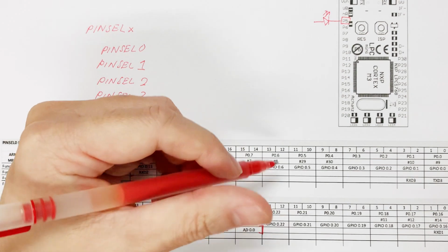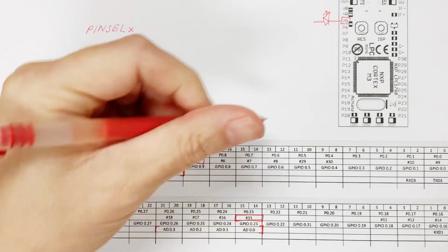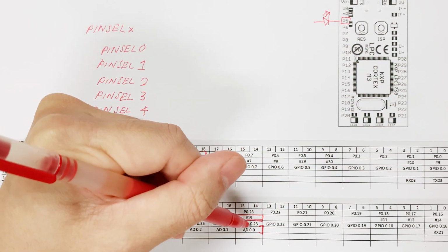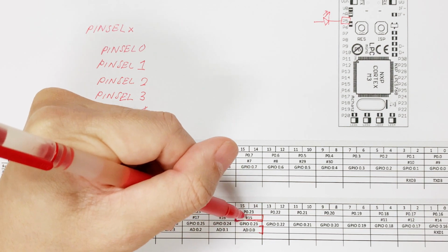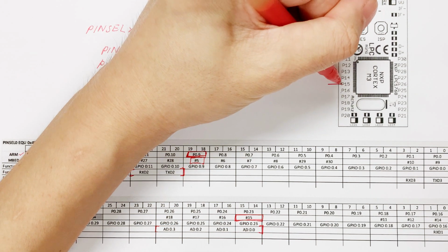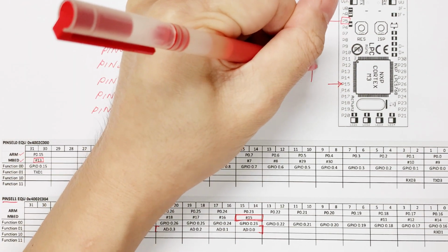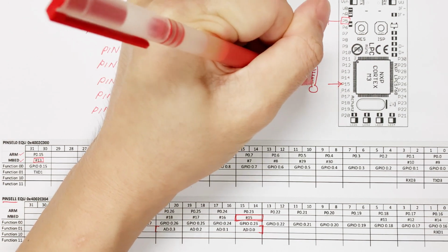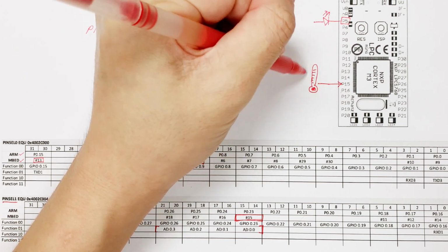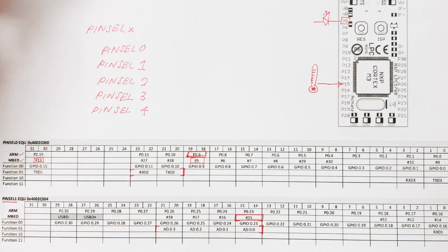At the same time, we can also look at the pins that are actually routed to the mbed module itself. For example, analog input 0 is actually available at P15 on the mbed module. In that case, for example, if I have a temperature sensor and I need the analog input to interface with this analog sensor, I have to select pin 15 on my mbed module.